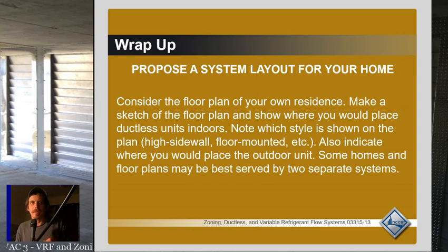I'm actually helping install a system in a house like that right now, where we're throwing air one way to get to one side of the house, then trying to circulate it back and throw it the other way to keep the air moving. And then in some spots we're actually putting little air shares, extra fans in to circulate the air in other rooms, so that we're moving enough air throughout the house, because that can be a very difficult thing to do with a mini split.